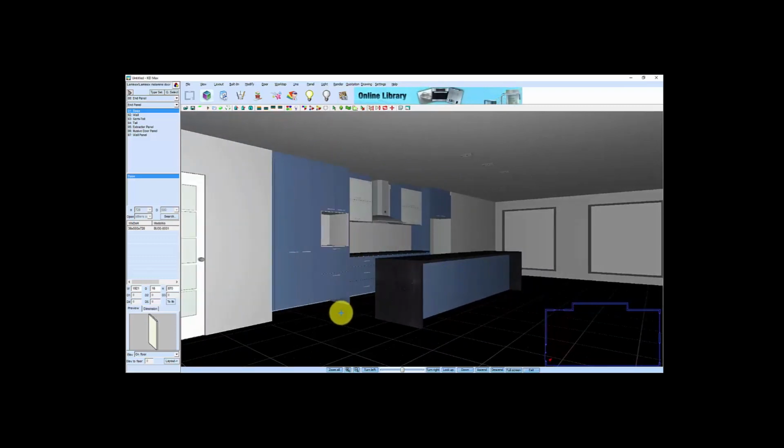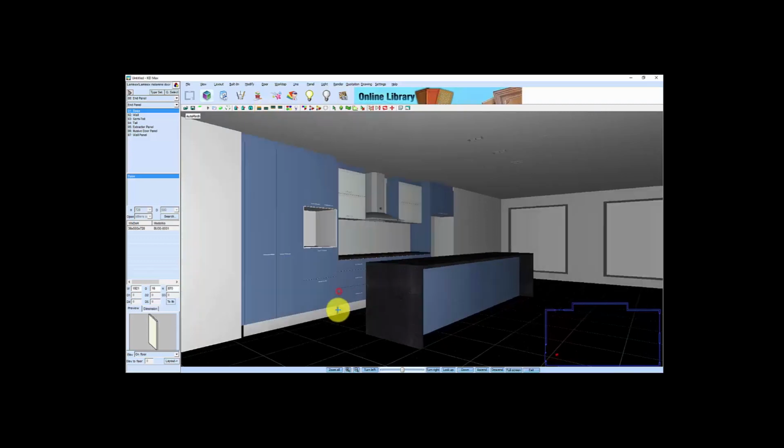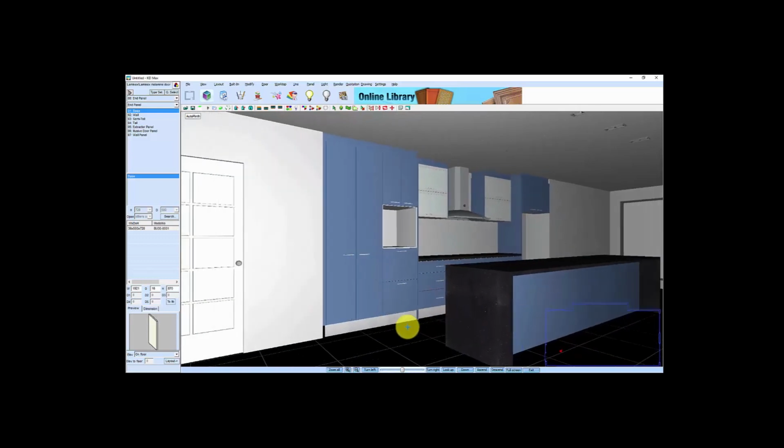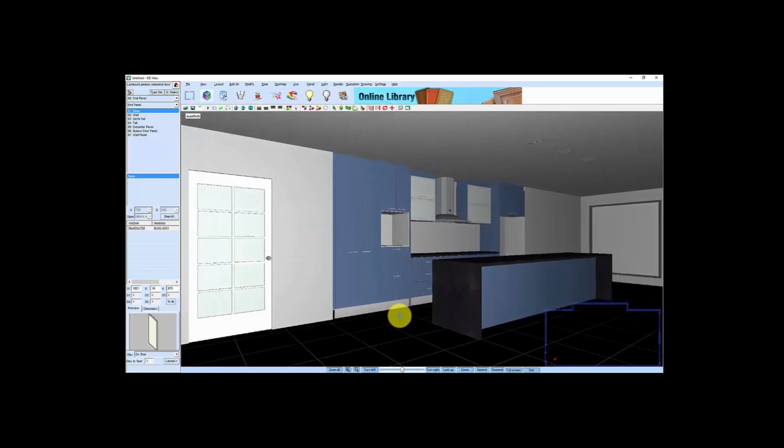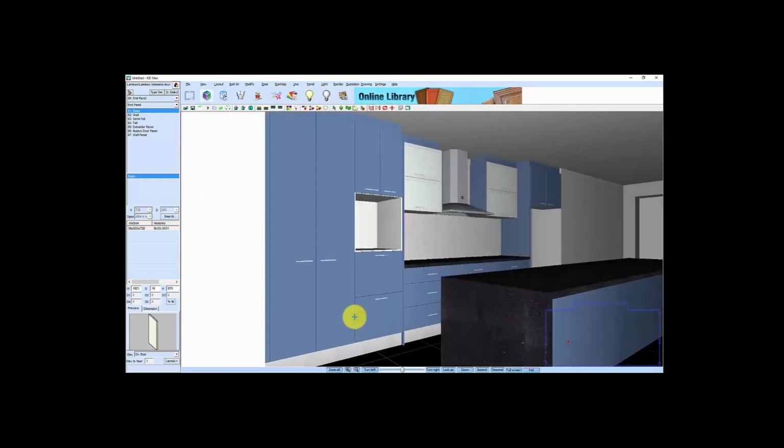What I'm going to do now is put in the kickers. That is an option with the kickers, the same as what we have with the benches. There's an auto install plinth option next door to it. Select that, and that'll automatically install the kickers with the color and the dimensions we set up. If it doesn't do all of it, you just go to line, create plinth, select units, select that one, and right click, and there it goes, it fills it up.